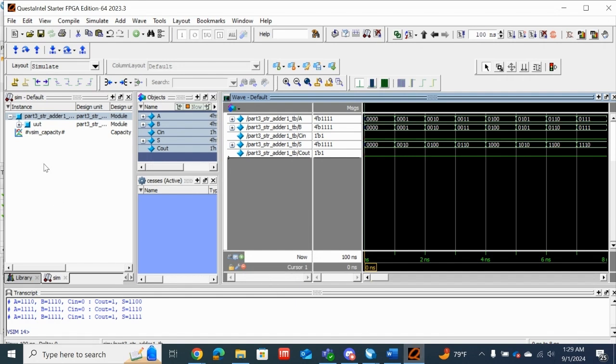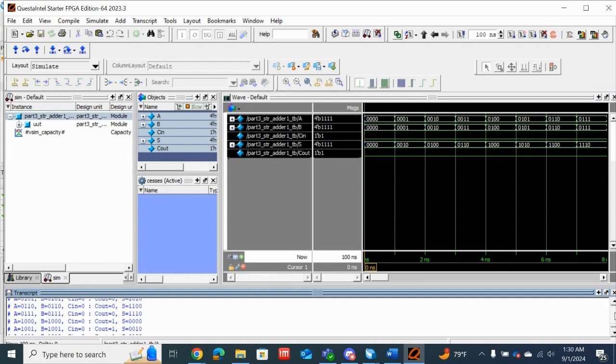After that, you just click on compile and click on the test bench and the other code, and then simulate it, and then add wave. Click on the inputs and the output parameters, and then after running it, this is the output waveform obtained. This is the same as the truth table, and this is correct. So you can see the outputs also here in the bottom.